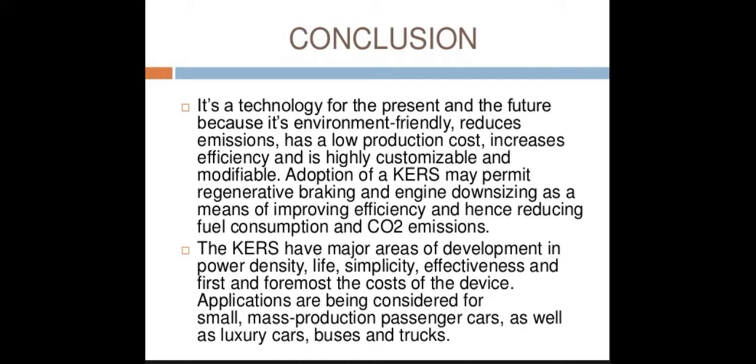Adoption of KERS may permit regenerative braking and engine downsizing as a means of improving efficiency and hence reducing fuel consumption and CO2 emissions. The KERS have major areas of development in power density, life, simplicity, effectiveness, and first and foremost, the cost of the device. Applications are being considered for small, mass production passenger cars as well as luxury cars, buses, trucks, etc.